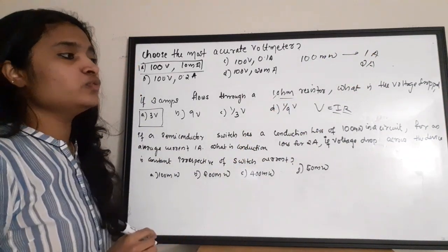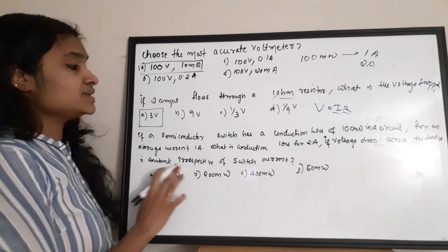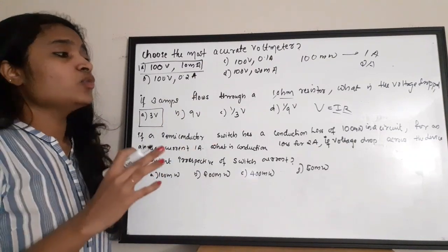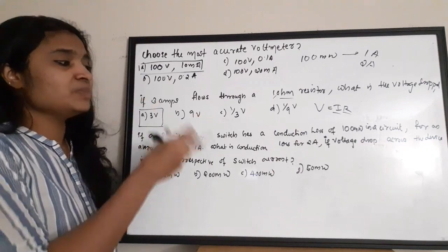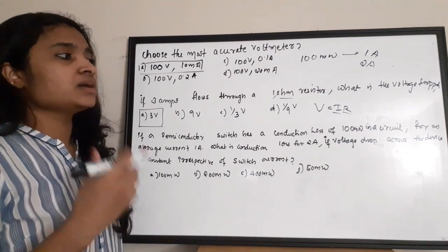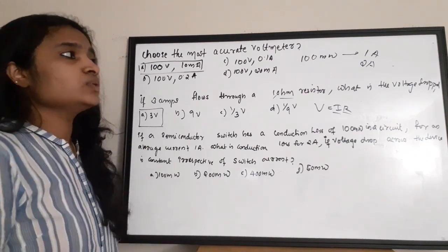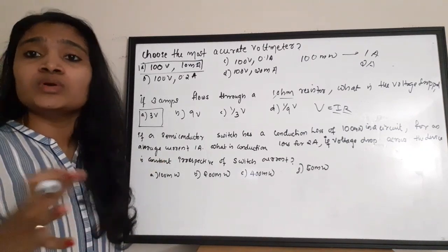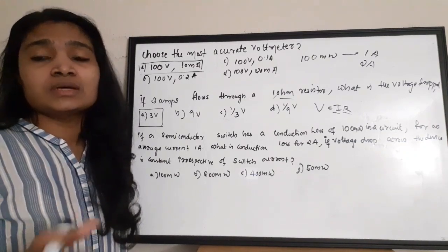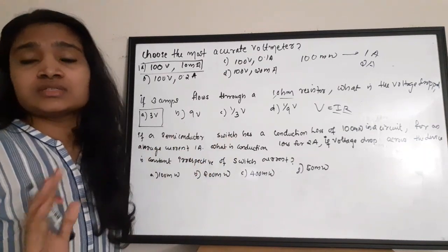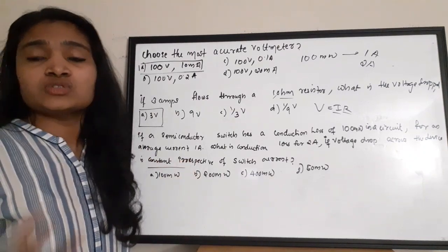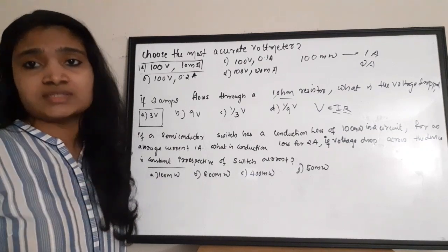It is given that the voltage drop across the device is constant irrespective of the switching current. Irrespective of whatever current may be, the voltage drop across this semiconductor switch is constant. So while calculating the conduction loss, we don't have to consider a change in voltage. There won't be any conduction loss due to a change in voltage. The voltage is considered a constant.